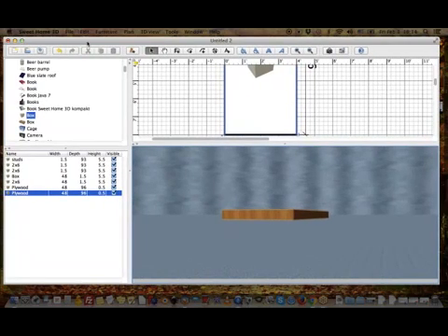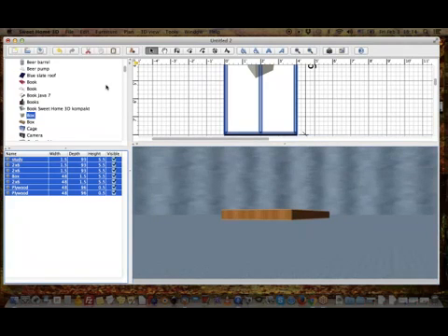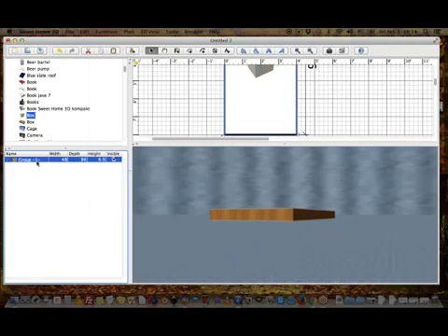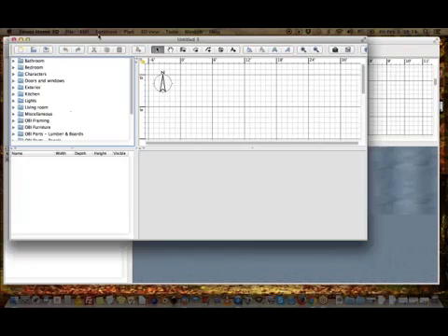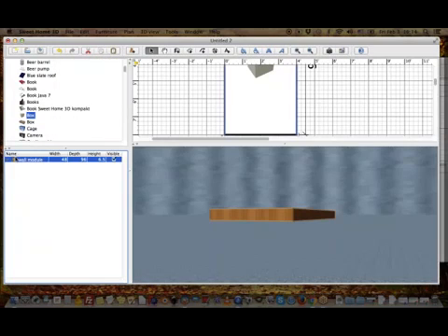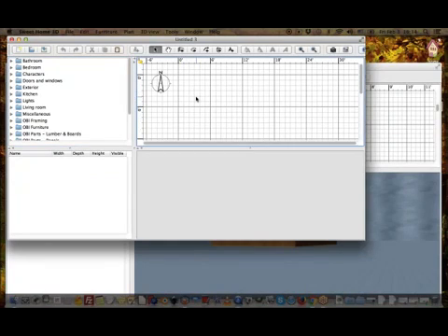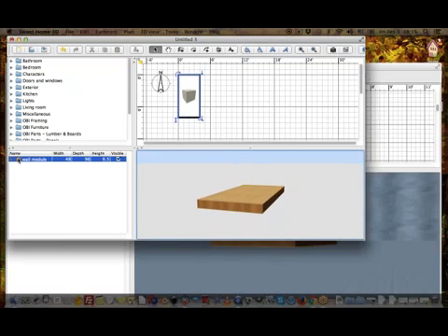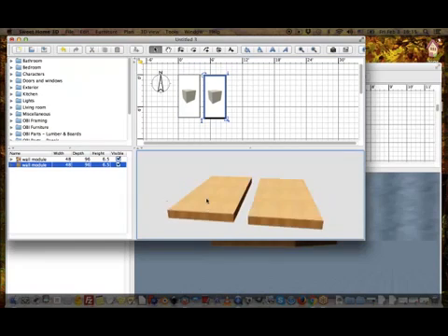All right, so now I have a module. What do I do with it? One thing I could do is select all of these, group them, and call this wall module. Then I'm going to create another Sweet Home 3D file, say new. So I have a second one here, and I can take my wall module from here and copy it onto this one. And boom, there it is, right? Say I want another one, I just copy this one and make a copy, and I can have a bunch of walls and all of that.